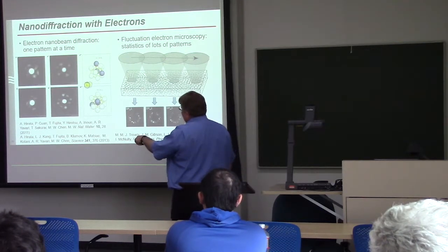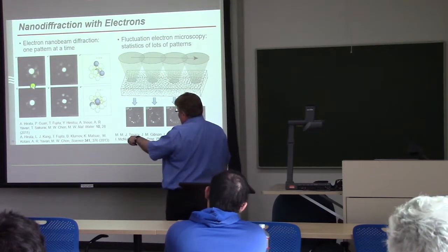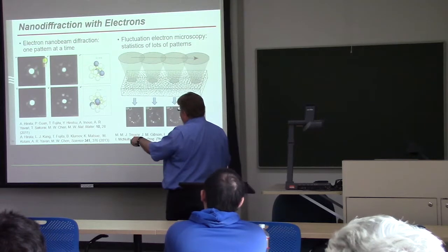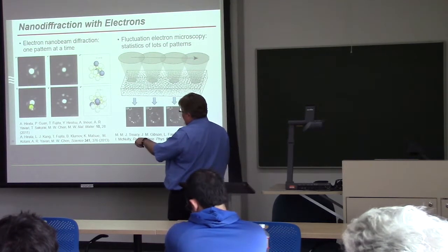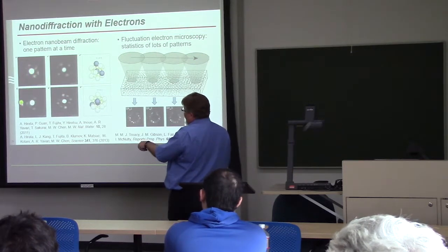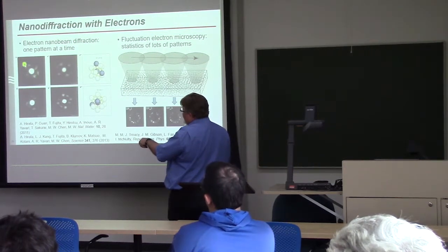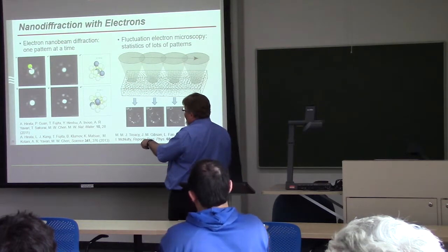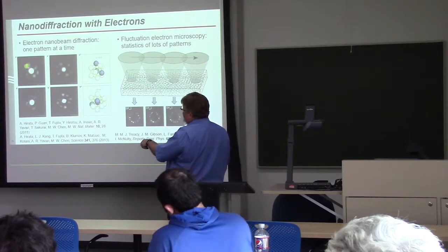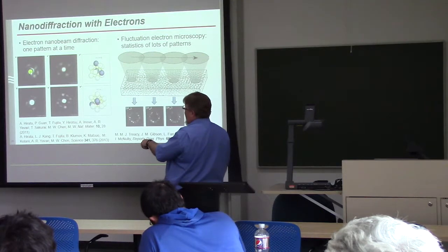And these are Angstrom beam diffraction patterns from a zirconium platinum metallic glass. On the left-hand side here are experiments, which show some sort of blurry features, but those features arise from diffraction from essentially one nearest neighbor cluster of atoms at a time.